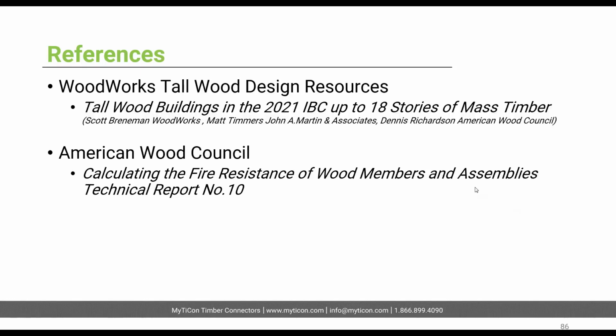So the other question is about the fire caulking. That depends on how you're housing the configuration. But we mentioned the fire caulking because that was what was used in the testing, and that's how the testing and results were from. In Europe, if 2 elements are connected, they're considered to be bounded if they have gaps that are smaller than 2 millimeters, so they're a little bit more lenient there.